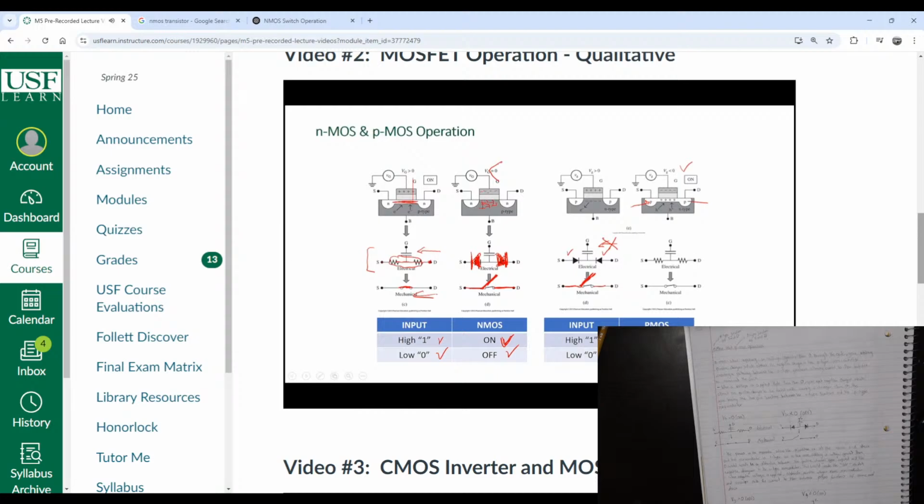So I hope everybody understands the general concept, the general mechanism that makes the NMOS and the PMOS transistors turn on. We apply a positive voltage on the NMOS, like here. We create an N-type channel, so we connect the drain and the source that are also N-type, and we turn it on. If you understand one of these conditions, you can describe all the rest.